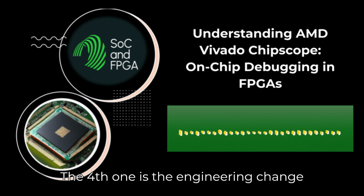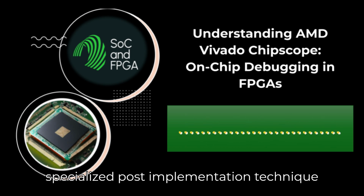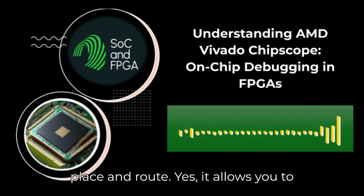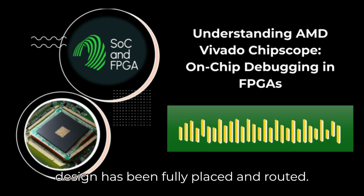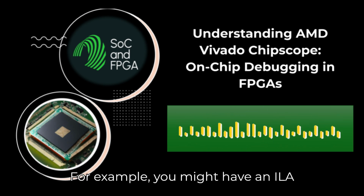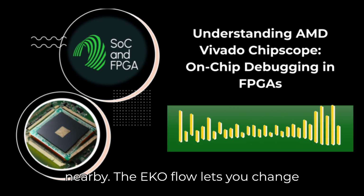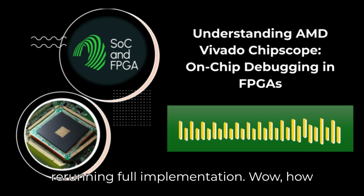The fourth one is the engineering change order, or ECO, flow. This is a really specialized post-implementation technique designed for extremely rapid debug iterations. Post-implementation, so after place and route. Yes. It allows you to modify debug probe connections after the design has been fully placed and routed. For example, you might have an ILA already in the design, and you realize you need to probe a different signal nearby. The ECO flow lets you change just that one probe connection without rerunning full implementation.